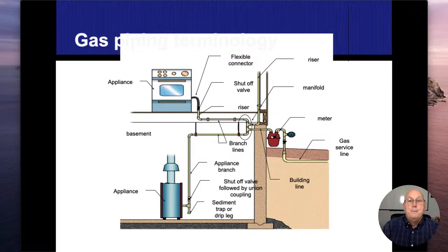All right. One of the nice things about doing these home inspection classes and the live events is I get to meet a lot of people that have a stronger expertise than I do in many different fields. And just recently, we had a natural gas guy come out. For me, the drip leg, I always thought of it as, when we use pipe dope to put all these pipes together, we're going to get a little bit of garbage, a little bit of debris, and I want to give that a place to land so that it doesn't come in and clog up or ruin my gas valve.